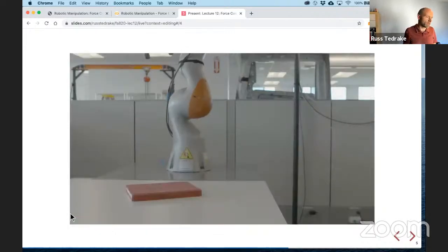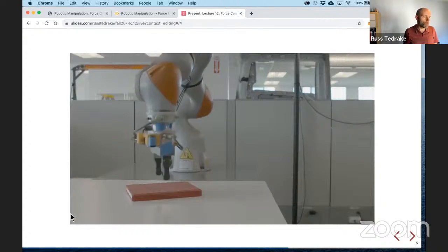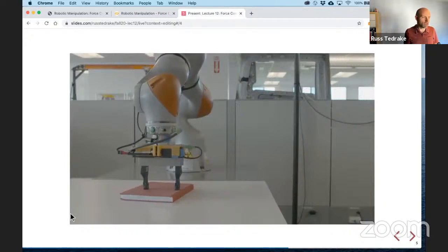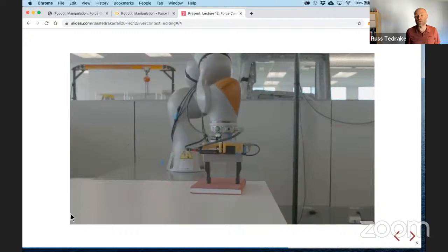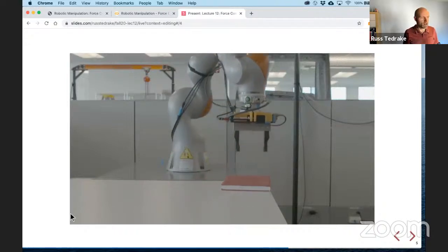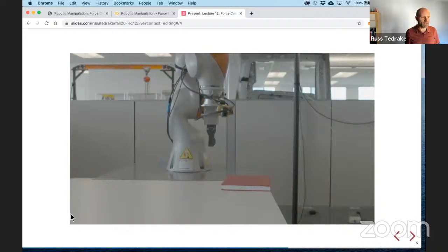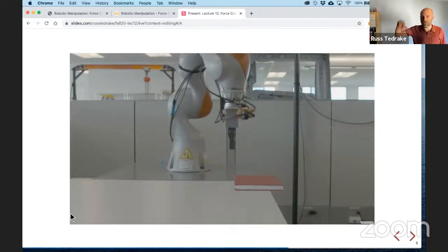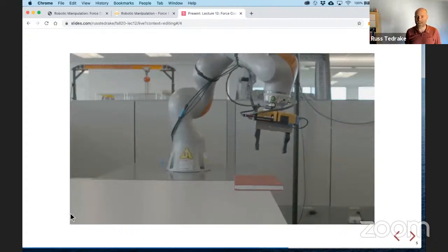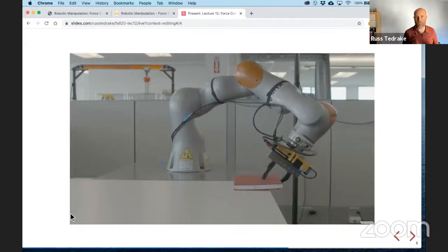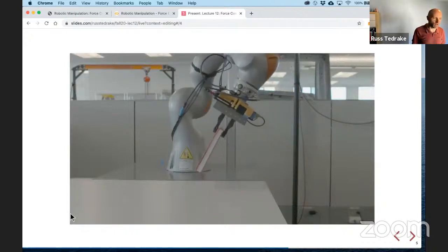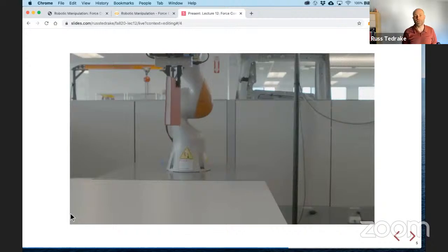on your slides or whatever, the problem with sliding on top is that, even right there, there was some initial time where the fingers slid and the book didn't slide. So the orientation of the book was unreliable during that maneuver. There's a really nice way to get the position of the book reliable again, which is, now that you're in the nice kinematic workspace of the arm, you do this uncertainty-reducing push on the side, which is just guaranteed to line up the book according to the fingers. So that's a really clever thing. And then now you're off to the side and you can pick it up in the thin orientation. So that's another example of the kind of stuff we wanted to do here.